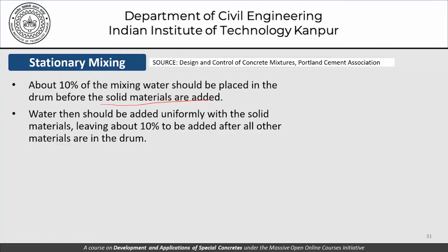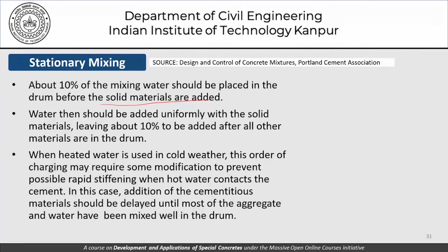When heated water is used in cold weather conditions, this order of charging may require some modification to prevent possible rapid stiffening when hot water comes in contact with the cement. In this case, addition of the cementitious material should be delayed until most of the aggregate and water have been mixed well in the drum.